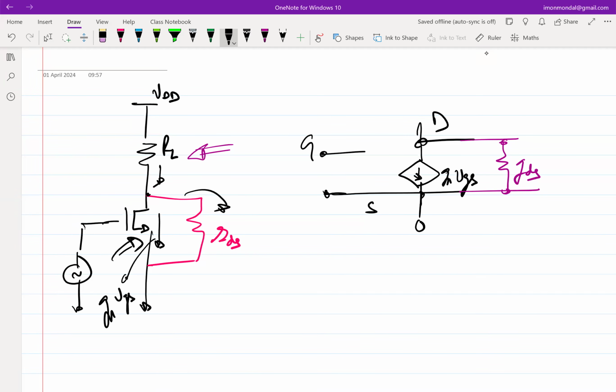And if we have to realize a transistor which can give us better gain, then we would like to divert all this incremental current into the load, and not its internal resistance. So for that, we had to put something here in between the transistor and the load, which can suck in all the GM times VGS current into itself and not divert it into the RDS.